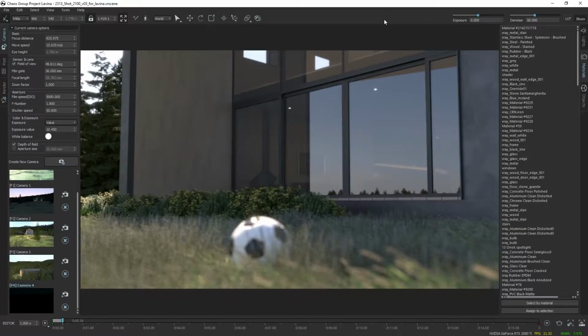For example, all these materials that we currently support are the Power V-Ray shader, the VR material, the V-Ray material. I was using the Power V-Ray shader. Imagine what version of V-Ray I was thinking. That was the first versions of V-Ray, so apologies for that. The regular standard V-Ray material, which is capable of reproducing the majority of materials around us in reality, is supported.